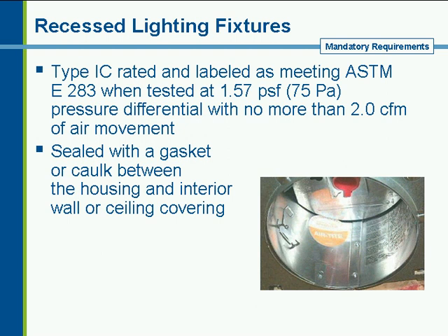Recessed lighting fixtures are required to be rated for insulation contact when they are up in insulation. There's a requirement that they be sealed with a gasket where they touch, for example, the drywall and the ceiling or whatever covering is there, to limit infiltration through that opening.